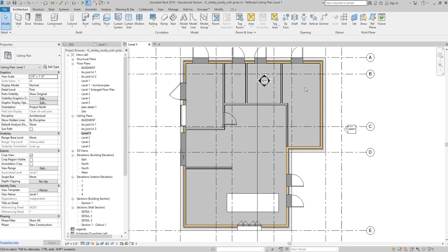So it's okay not to have one structural element for the ceiling and then add the grid or gypsum board or whatever you want it to be. You can just add your ceiling per room, per ceiling type, whatever you want it to be, and that's perfectly all right because the structure is actually the floor above for that ceiling.